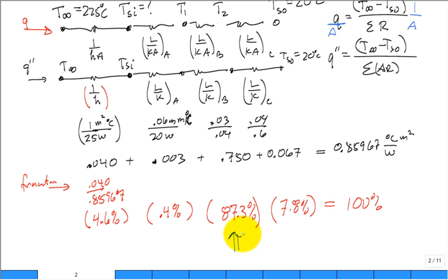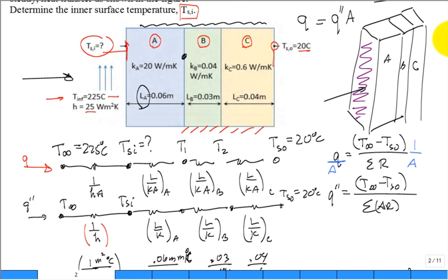I've seen it where you get a complex problem going and people start debating and they say, oh no, to do a better job, we really need to promote the heat transfer. We need to increase the thermal conductivity of material A. They'll start arguing: if you increase the thermal conductivity of material A, will it significantly reduce the overall thermal resistance of this system? The thermal conductivity of A is already pretty high. But if you could get a change of a little bit of the thermal conductivity of B, it would have a big impact.